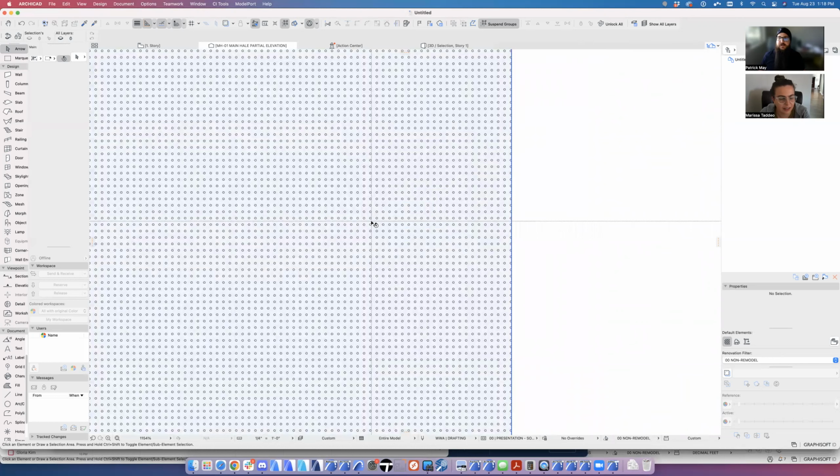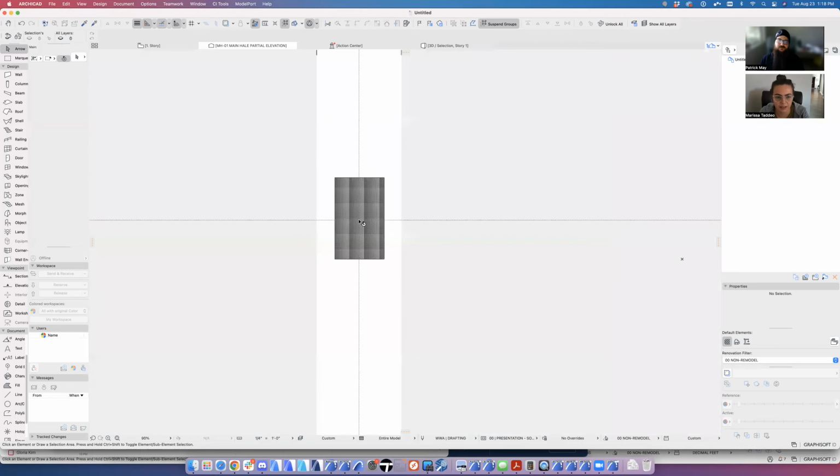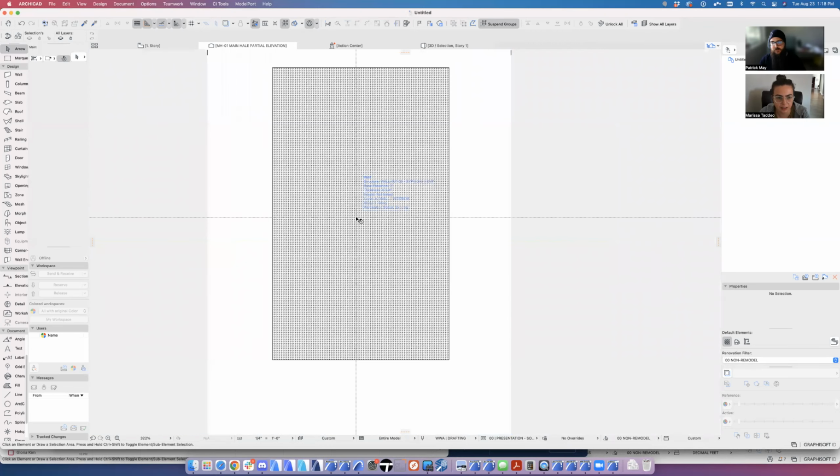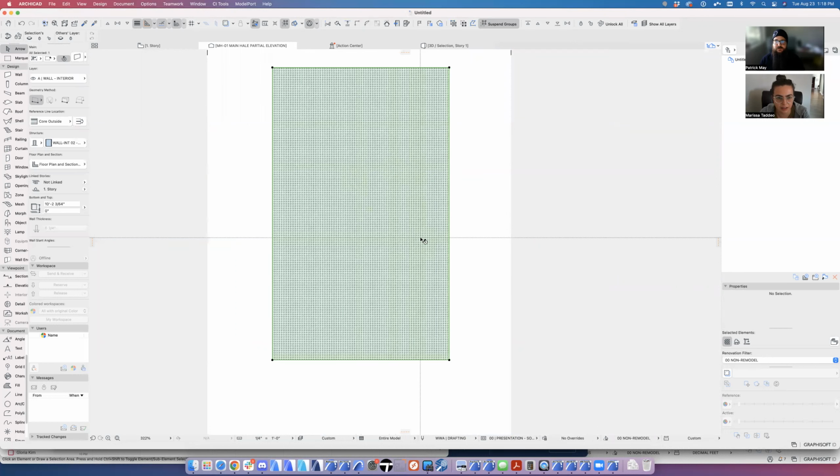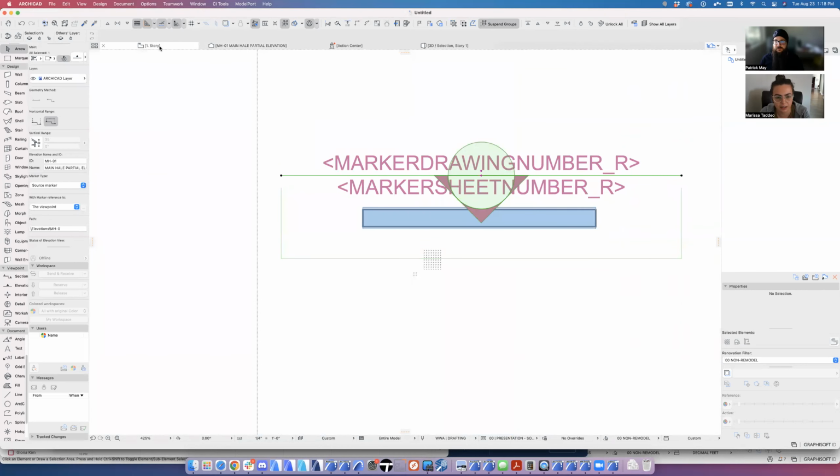Gotcha. That would be the ideal way to work through these surface interior elevation things. I know that drafting patches and fills happen, but depending on how prolific in the project this is, it might be worth it to invest the time. At the very least, create that custom fill so that you're not drawing 10,000 or 1,000,000 circles over an interior elevation.